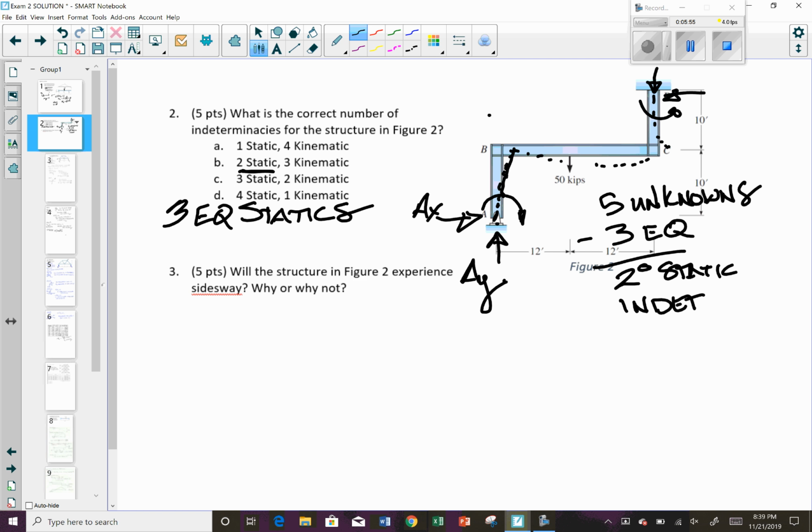So we're going to have one displacement here, one displacement here, and that displacement is going to be the same. And now as I go through this, I realize we've got a rotation here, theta B, and a rotation here, theta C. This is rotation A. So this is actually 4.